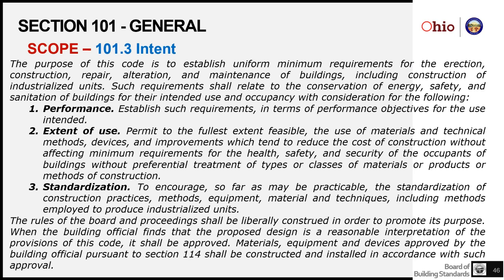3781.061 gives the authority to the zoning inspector to issue a certificate out of the zoning rules to exempt a specific building. The building official can either make the determination themselves through 3781.06 and exempt that building, or they can accept the certificate from a zoning official that has exempted that building for agricultural purposes as evidence of exception from complying with the Ohio Building Code. Now,